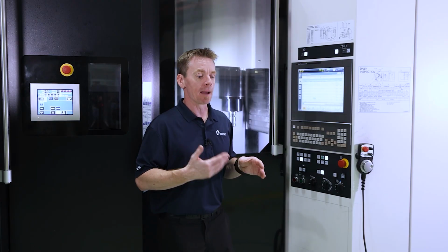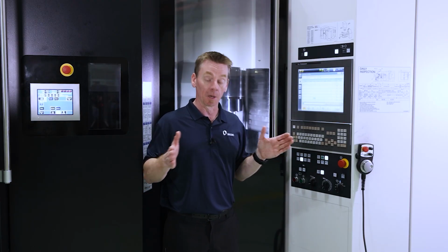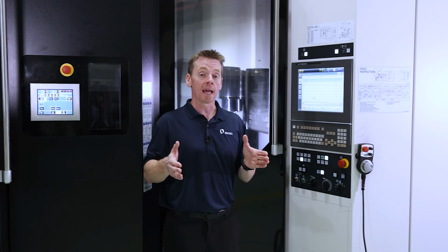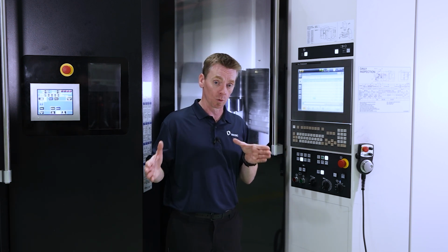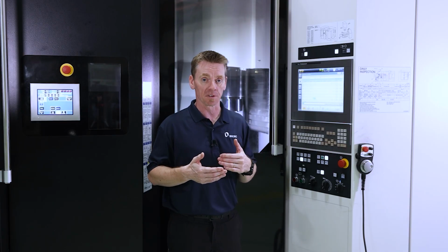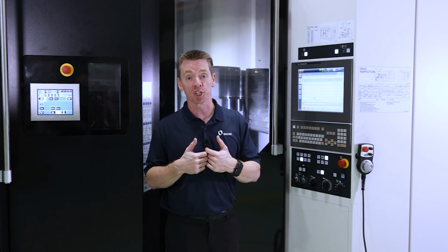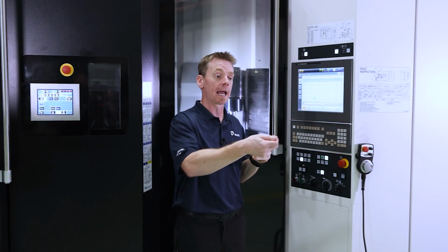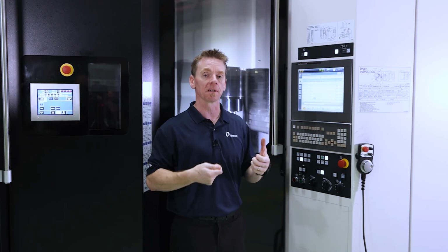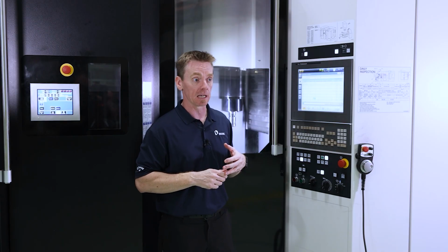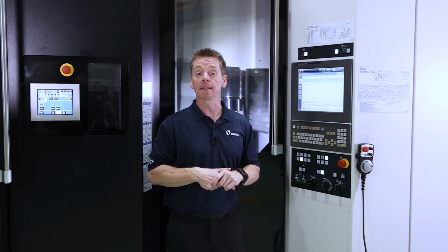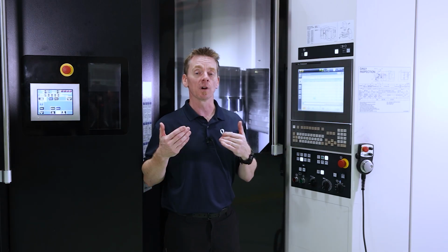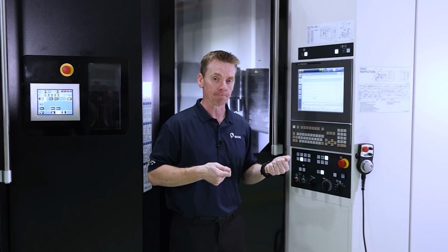Let's say you set up a bunch of different jobs. You're not running just one job. You do a high mix of work, and you may not have a set tool numbering system that always puts these tools in the same pots. Or you may have more than 118 tools total, so you end up pulling out certain tools or adding tools into the system. And it can become confusing if pot number 119 one time is a 1/2 inch end mill, and next time it's a 1/4 inch end mill. There's nothing to differentiate. It's just tool 119.